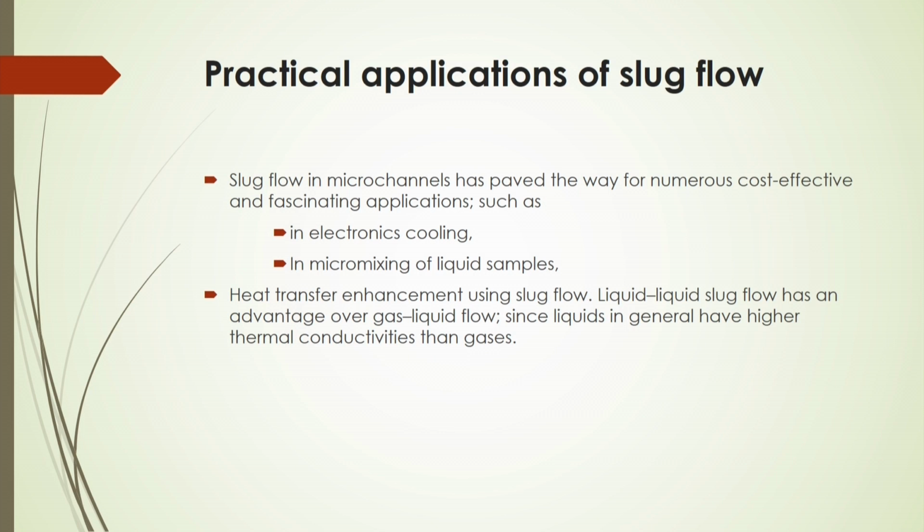Heat transfer enhancement also can be done by the slug flow system. Liquid slug flow has an advantage over gas-liquid flow, since liquids in general have higher thermal conductivities than gases. And micro channel based heat transfer equipment is being developed nowadays based on the advantages of the slug flow in the micro channel system.